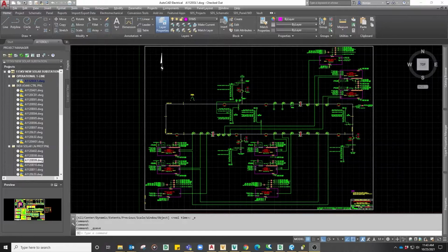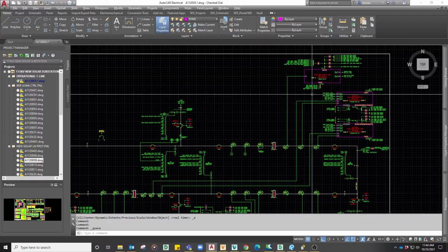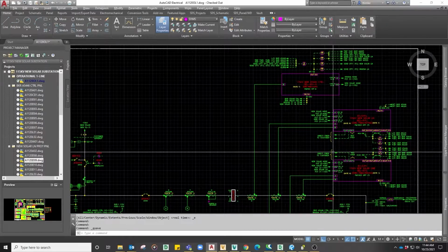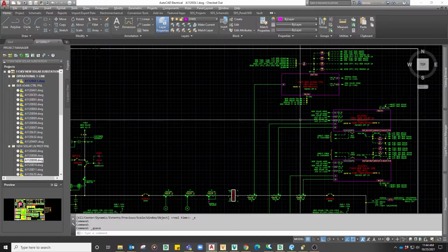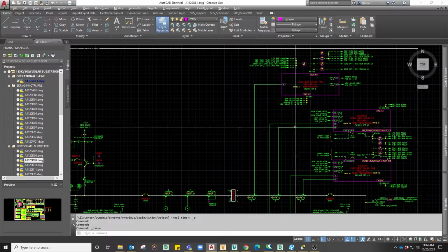This is the same 3-breaker ring bus project from our last video where I created the panel sub-projects for the North Bus Breaker A5446 and its related equipment. I have a relay for our breaker control panel and a dual 411L line protection panel right there. There will be multiple cables that are going to run between these two panels for tripping, breaker fail, bus potential, and line potential.